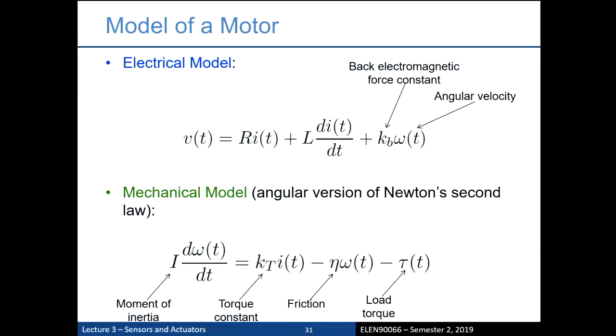So in other words, the faster the thing goes, right, you're powering the motor. So you're powering it up with the current, with the voltage, but it's also generating voltage as well. So in the stators or the windings of the motor, it's also resisting you, if you like. Resisting is probably a bad word, but it's acting as a generator at the same time as a motor. So you've got that term there.